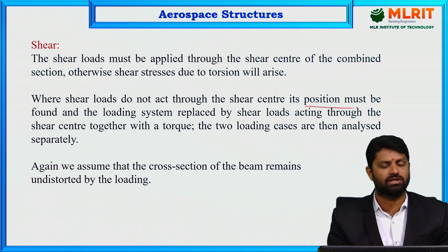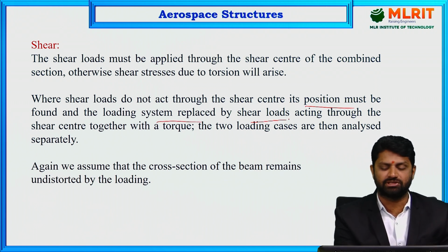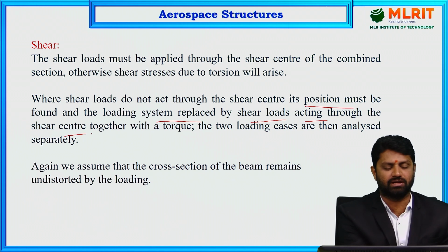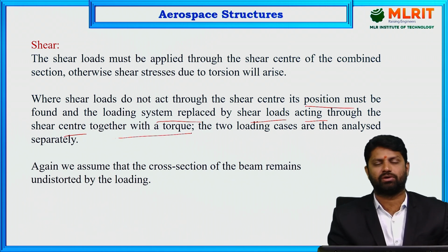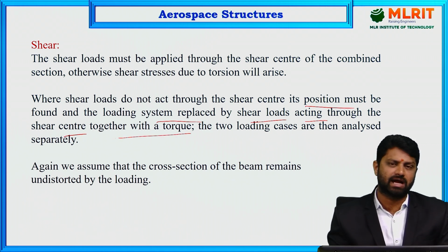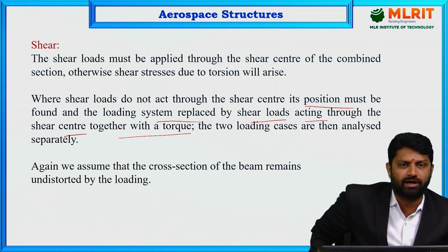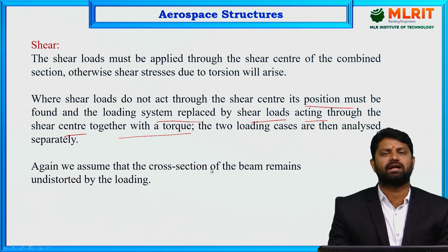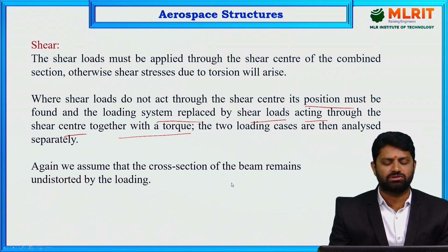If the shear loads are not acting through the shear center, then again we need to find out the position of the shear loads where they are acting, and the loading system is replaced by the shear loads acting through the shear center together with a pure torque. So the shear loads have to act through the shear center, followed by the torque, and therefore the two loading cases are then analyzed separately.